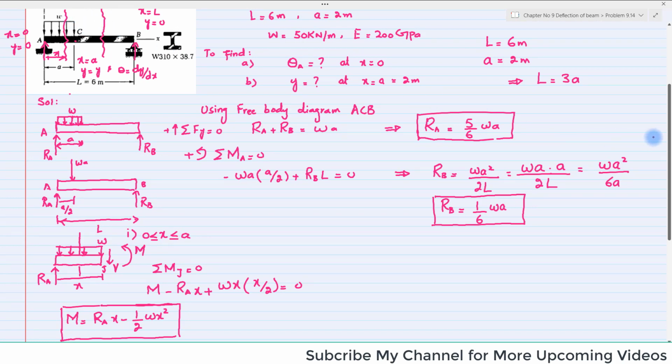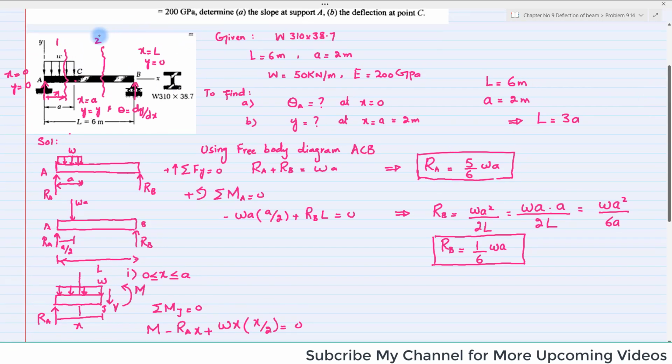sectioning the beam at point 2. So we will take the section at point 2. Let this distance be x. Clear? So we will take this remaining section, and I will draw the free body diagram of the remaining section. So this is RB. Clear? As the total length is L and this is x, this distance will be equal to L minus x. Clear?